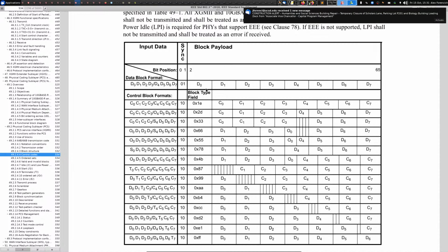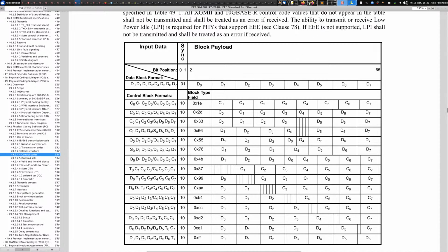And you see this as well with like a UART, for example. You have start bits and stop bits. And it's the same idea there, right? You're sending the bits down the wire one at a time. You have to determine where's bit 0, where's bit 7, how do we get them in the right order? The start bit and the stop bit allows you to do that. So that's the same idea here.